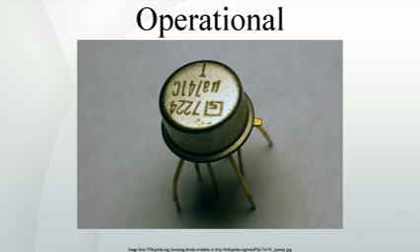Other varieties of op-amp include programmable op-amps, simply meaning the quiescent current, gain, bandwidth and so on can be adjusted slightly by an external resistor. Manufacturers often tabulate their op-amps according to purpose, such as low-noise preamplifiers, wide bandwidth amplifiers, and so on.